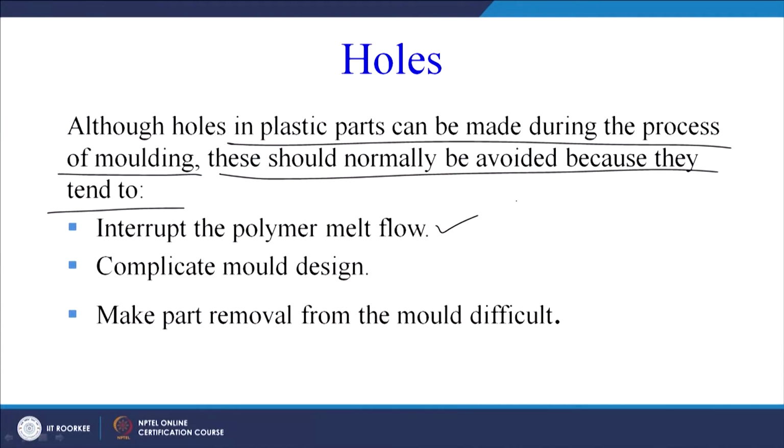Why? Because they interrupt the polymer melt flow, complicate the mold design, because you have to place them in the mold and ensure that they do not move when the plastic melt flows into the mold cavity, and make part removal from the mold sometimes difficult.